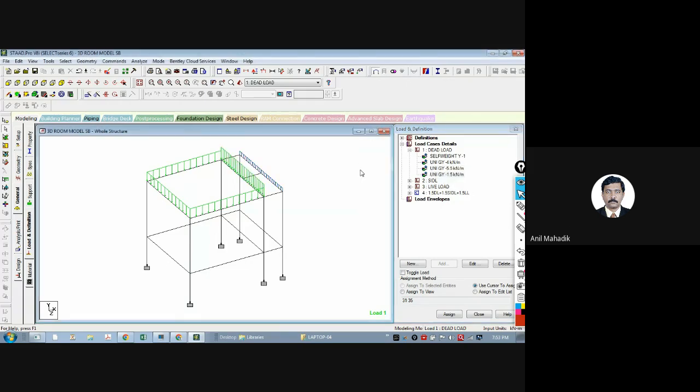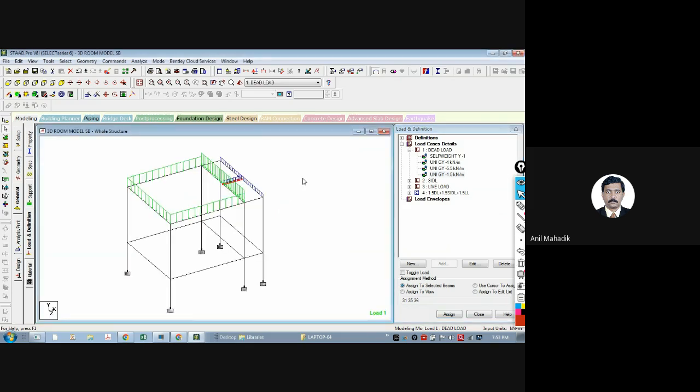You can change the loads. I'm not going into detail regarding the loads. Okay. So let me take any load here. You know the load path and what load should be there. Once you add this beam, the load pattern will change. Please remember, this will not be one-way, it will be two-way load. Okay. I'm just arbitrarily taking some load on this. Now run this.